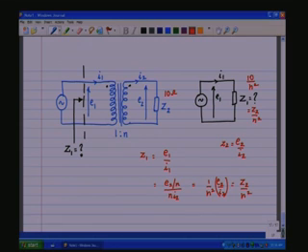A real 10 ohms load is seen as 10 ohms by N square by the source. So, actually the transformer is doing a transformation on the impedance value, and that is a very powerful feature, especially when you want to match the impedances of the primary side circuit and the secondary side circuit.